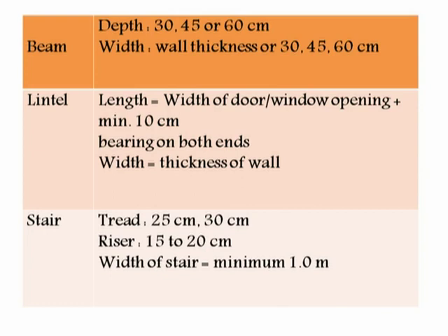Next is the stair. The stair has a dimension of a tread of 25 to 30 centimeter. Riser is provided 15 to 20 centimeter. The normal size of the riser is 15 centimeter and normal size of the tread is around 30 centimeter. The width of the stair is to be kept minimum 1 meter.